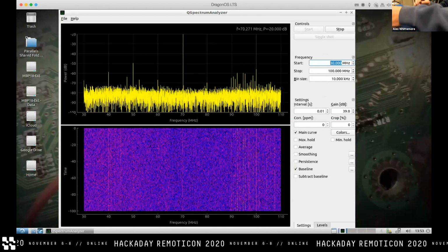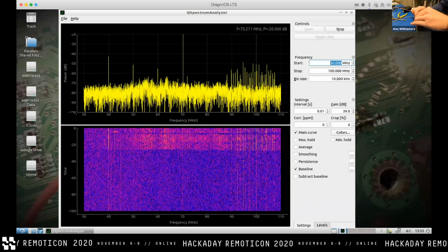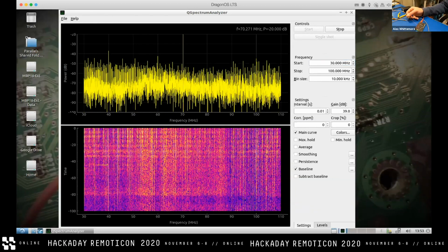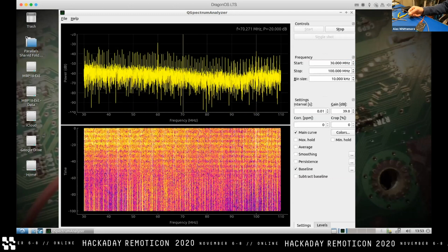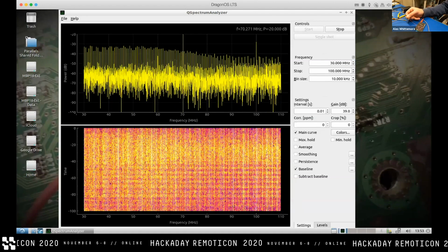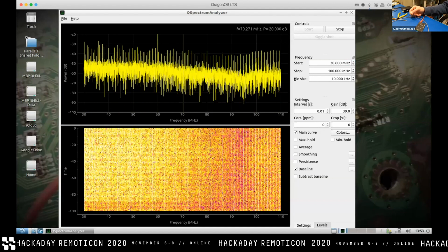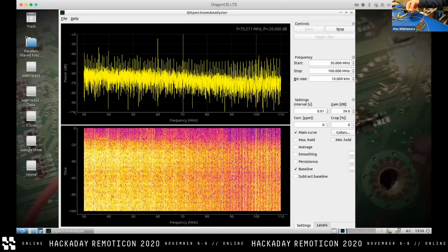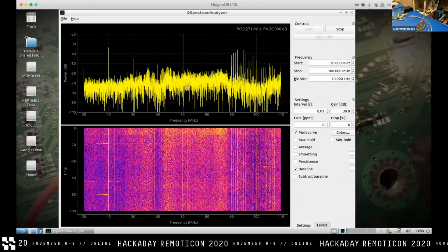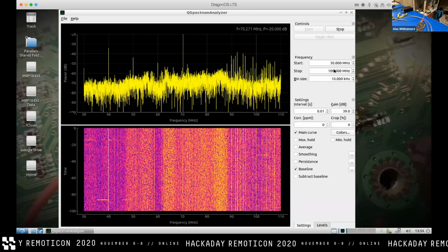It looks like it's a stuck cursor. Yeah, I think I would ignore that. Anyway, let's plug in our big wide probe and look around. We've got basically the RSA speed. Granted, it's just on a peak line, but over that massive bandwidth, and we can see all of those peaks. So the HackRF is really, really good for this kind of work because it supports great pseudo swept spectrum analysis features.